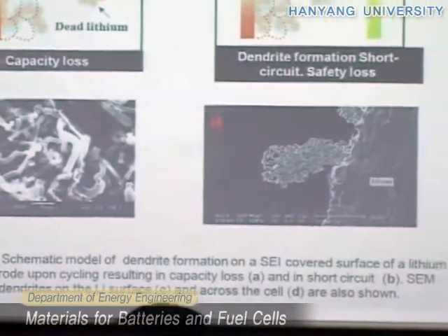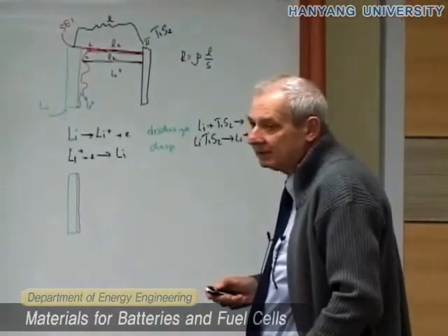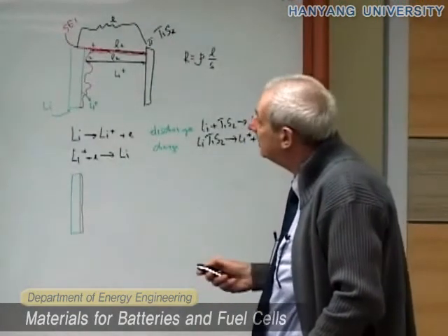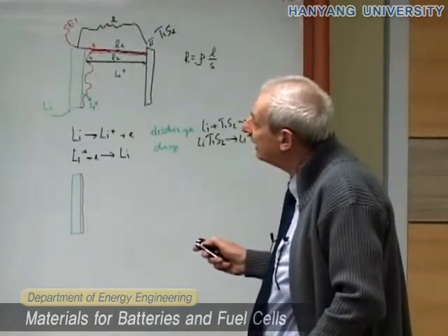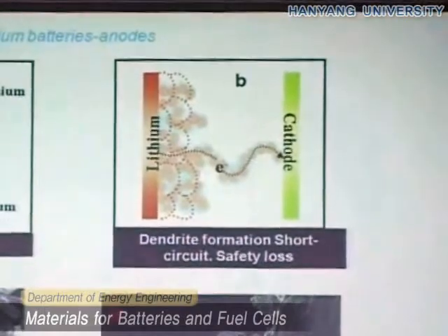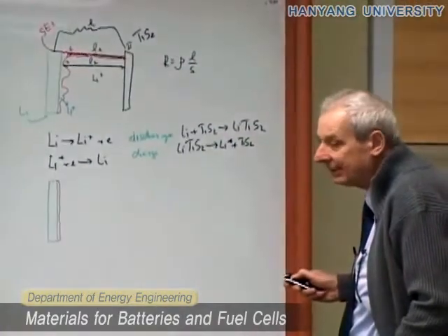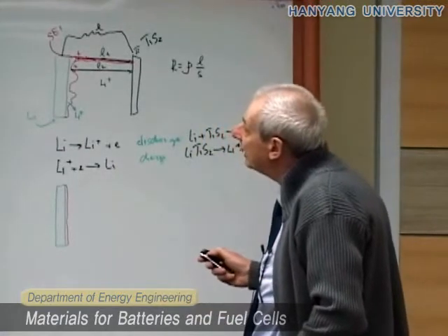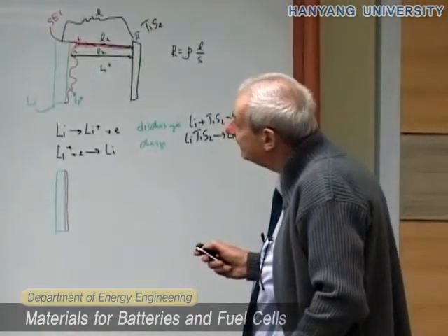So at the beginning of the lithium battery evolution, lithium metal was used, but quite soon accidents happened, fire and explosion. At that time this was not so clear, but now the mechanism is very clear, and we know now that we cannot use lithium metal unless we are sure that the film formation is very uniform and we don't have dendrites growing. And this is the reason why the technology moved quickly from lithium metal to graphite.